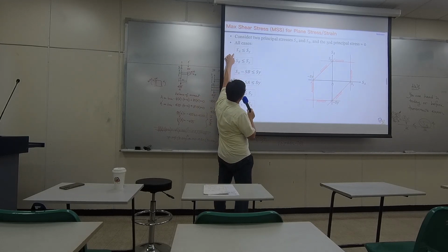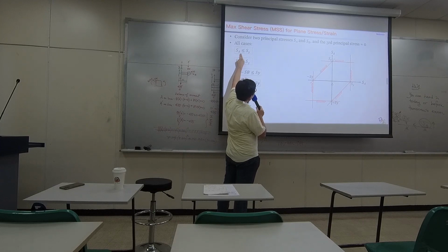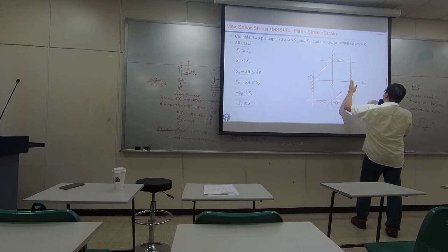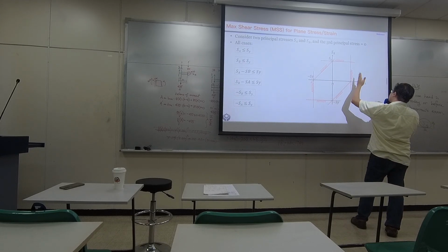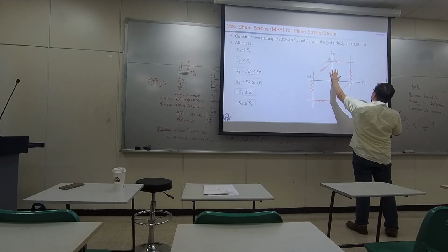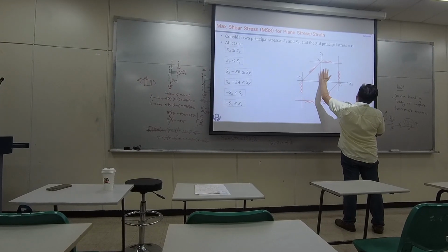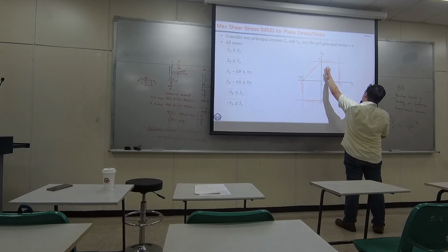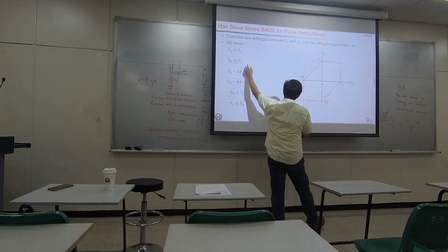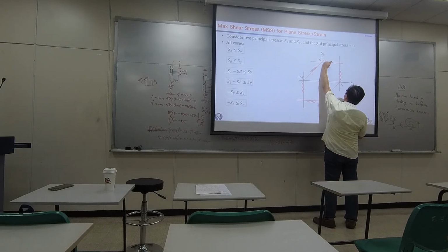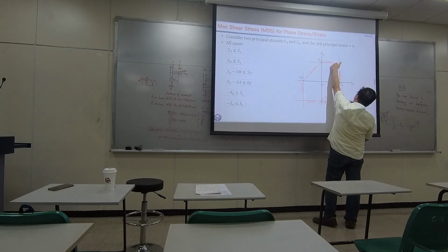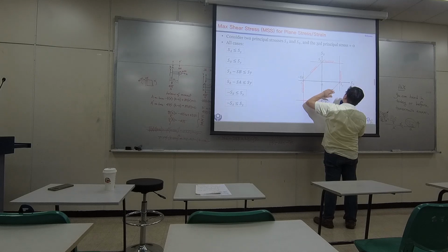And the first equation I had was SA must be smaller than or equal to SY. So that gives me a straight line like this, vertically. And on the right hand side, it's a fail region. On the left hand side, it's a safe region. So we want to have a design on the left of this particular vertical red line. For the second equation, it's a horizontal red line right here. SB must be smaller than or equal to SY. So you can stay on this red line, the horizontal one, or below. You cannot go above.